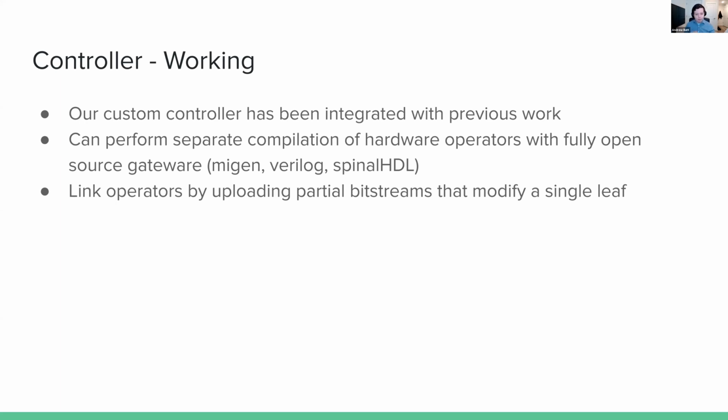And we can perform this separate compilation, and we can generate full partial bitstreams that we can upload separately to the board. And this allows us to only modify a single operator in our graph and get this separate compilation and linking.